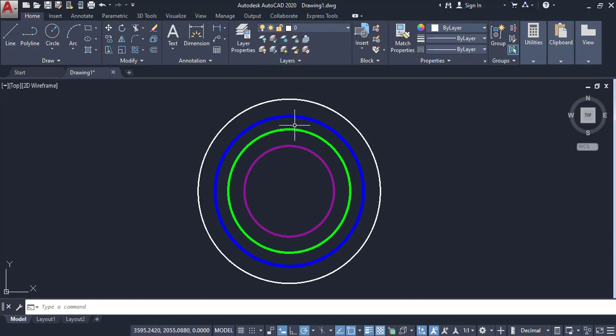This automatically shows us the frozen layers. Unlock layers. This is the unlock layer icon. Before, I locked some layers, then unlock again. Click on this lock icon, then click the object, then again and again.